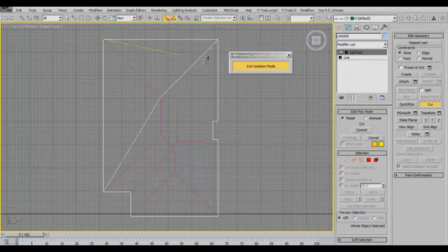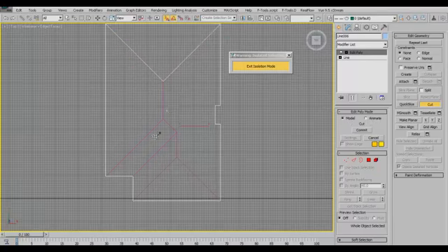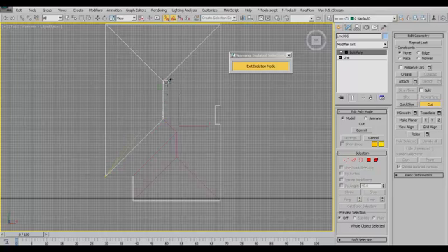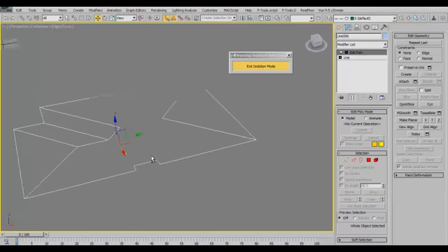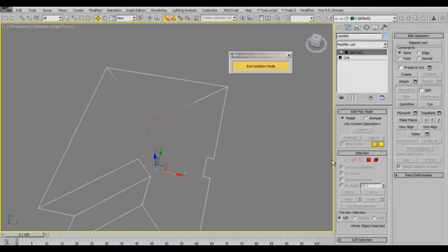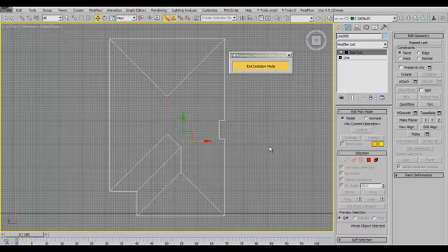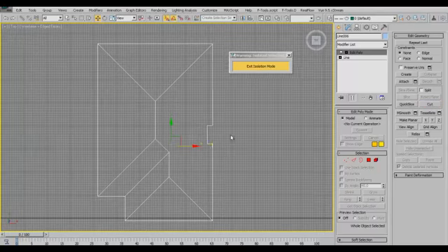I did this method in the previous tutorial, the very first tutorial I did on this website, which you can follow if you don't really get what I've done here. So to get the roof out, let's see if we have it correctly, and I think we need one more cut. Let's go back to our top viewport, cut. Yeah, fine, we have that completed now.